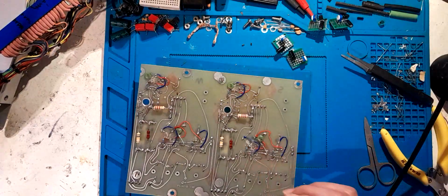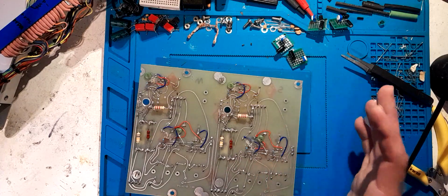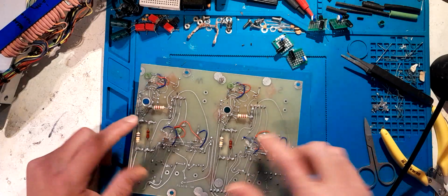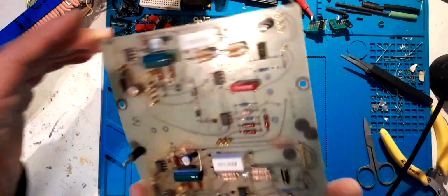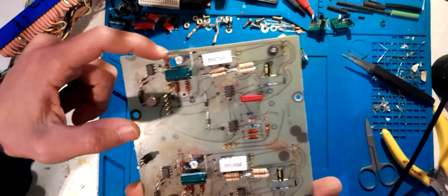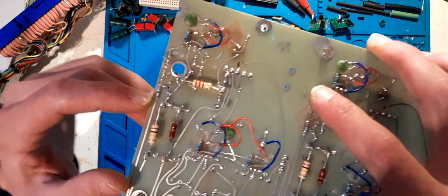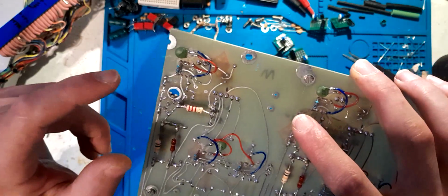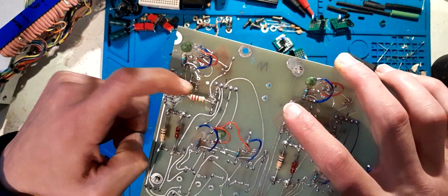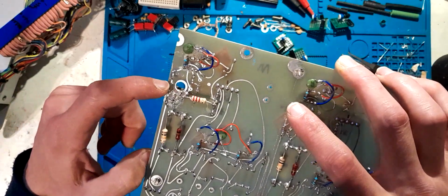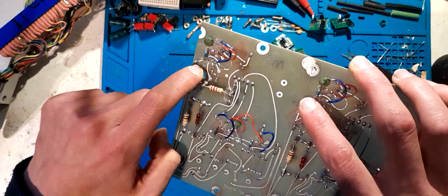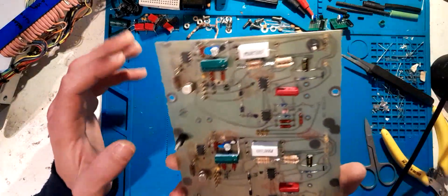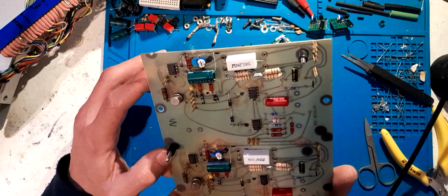Alright, so this is my solution for the TL431s, just the normal TL431As. I don't know if you can see what I've done there. That's the pot and the TL431, and that's how I've wired it up in between the two tracks, like I said I was going to. Now, because there used to be a Zener diode across those two holes there, that leaves a free hole there and a free hole there, and I've drilled another two holes there. The reason I've done it like that is when I end up getting the exact capacitor values I want to...